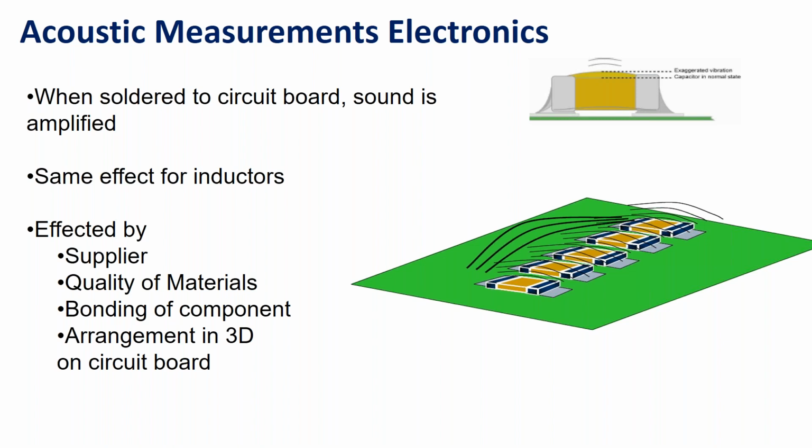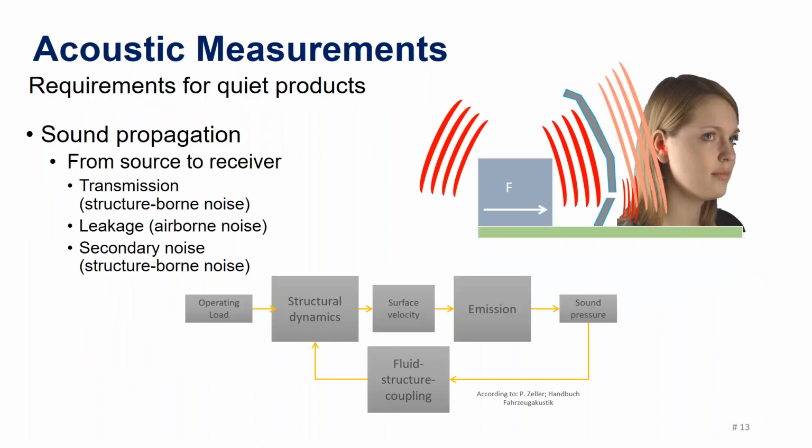The same is true for inductors. Inductors and capacitors have this piezoelectric effect where they vibrate and can cause this problem. This is affected by the individual devices, quality materials, how they're bonded and arranged on the circuit board, and just the 3D arrangement on the circuit board.